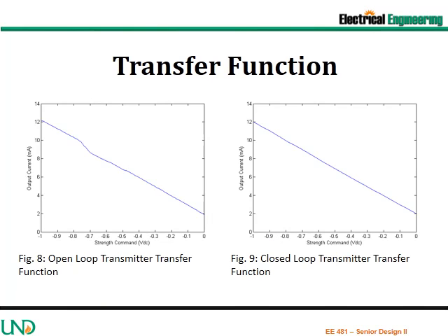The laser diode chosen has capabilities of a Class 3B laser. Safety is required as injury may occur with no warning. The benefit of the current buffer concept is that the maximum power is limited to 3 milliwatts, with a nominal average power of 1.5 milliwatts. Reclassification of a laser class cannot be performed without actually measuring the output power.